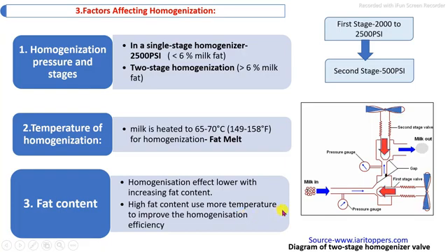You can see two-stage pressure homogenization, in which the preheated milk is passed into the first stage, this is the first wall, and then the milk passes into the second stage, this is the second wall. This wall is adjustable as per our pressure requirements. There should be a provision to maintain the flow rate and pressures, and reciprocating pumps are also provided.